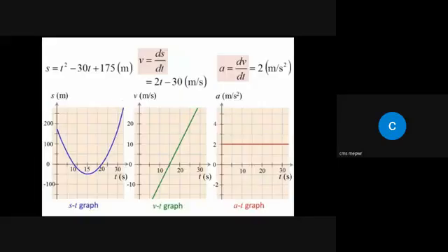Okay. So again, this is a continuous motion equation. For displacement, we have this equation, and when you plot it, you get this curve. In this case, for the whole time range from start till the very end, only one equation is used, this one. If we take its derivative, we get this one, and when we plot velocity based on this equation, we get this plot. Again the same equation is used, so we have a continuous motion, meaning one equation continues for the whole time range.